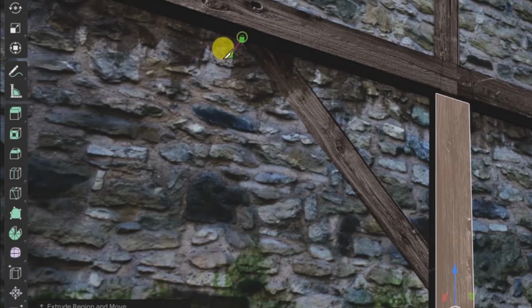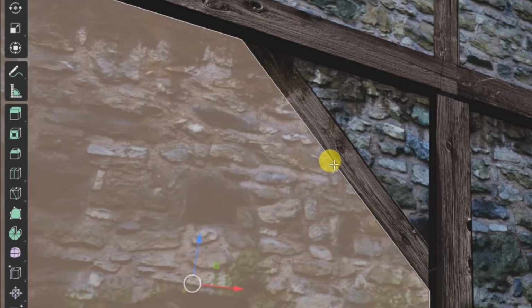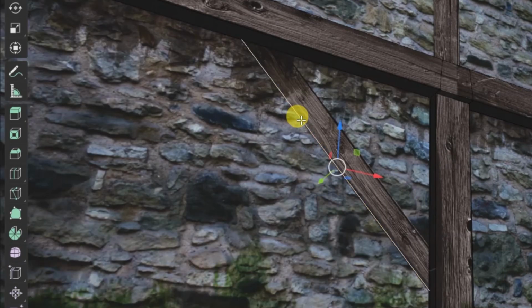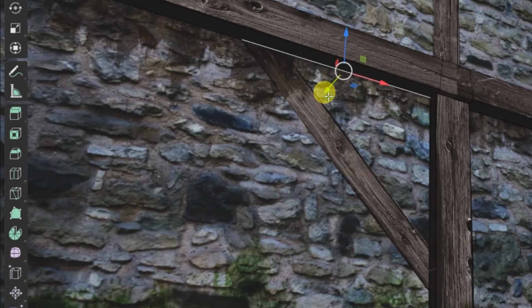So I'm just going to click right about there, and I'm just going to extend this little magenta line over here until I go to this edge there, and I'm going to click there again. Now you have to hit the Enter key or Return key, or I think left mouse button will also work there. Now I've got a new face there. I've got this face and I've got this face, and if I'm in edge mode here, I can select that edge. We need to do that again, however, because we need to hit our K button here, and I need to go up to this top side here, come down over here, and come down over here, and I'm happy with where I put those cuts.